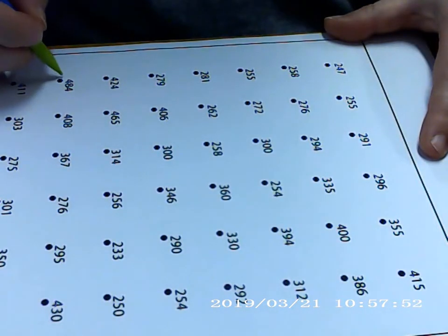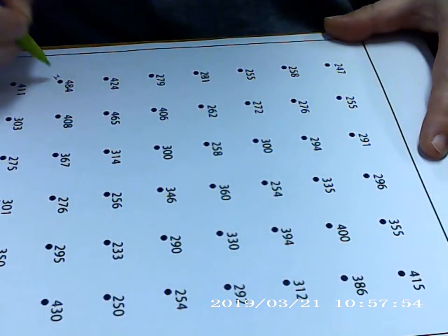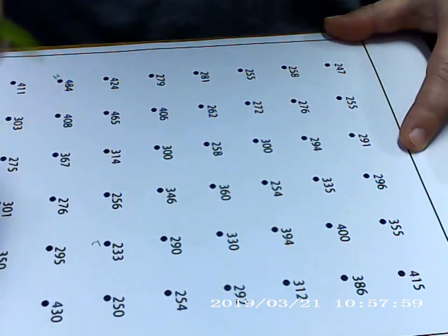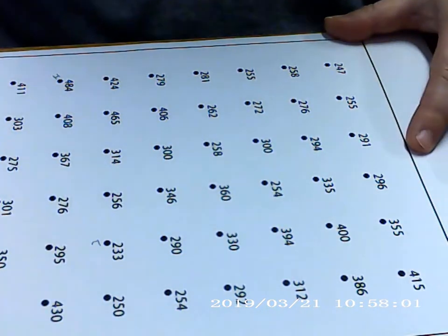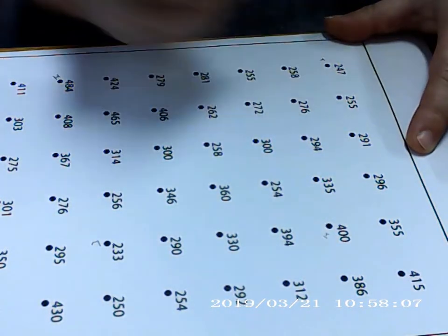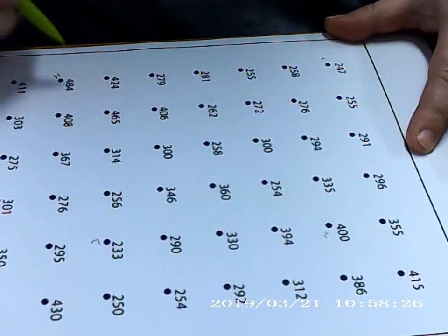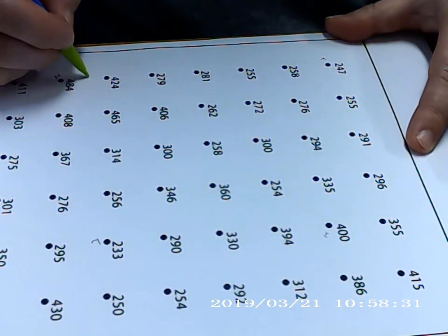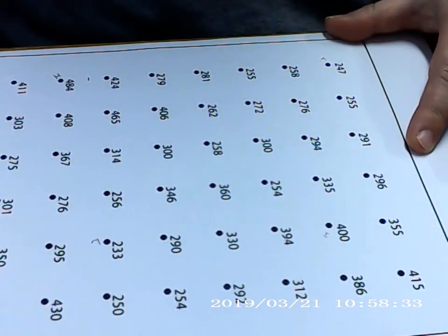Now that we have our method of contouring between data points, we can extend this to a map. We will assume that this map is of topography, so hills and valleys. In this case, we have evenly spaced data, so in order to start we need to look for the steepest gradient. We begin by identifying highs and lows on the map and marking these with a little label to help us see the shape of the data. Looking at the range of data, if we use a 50 metre contour interval, we should get 5 contours.